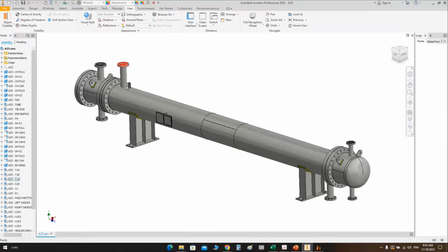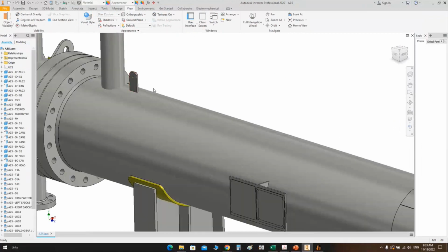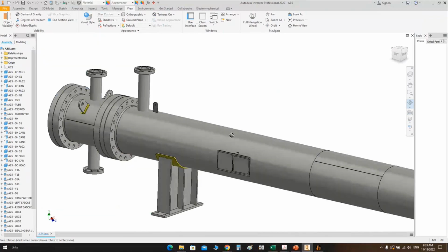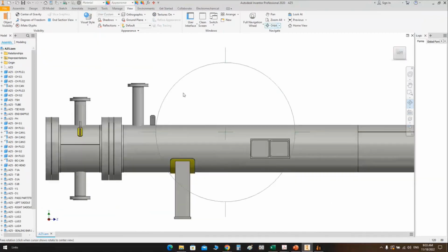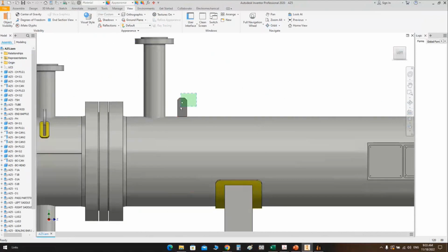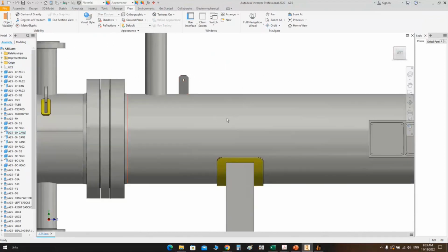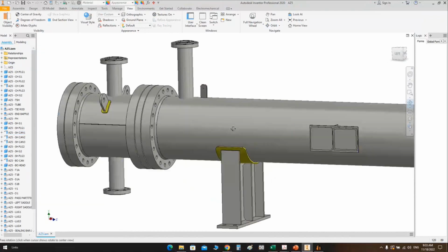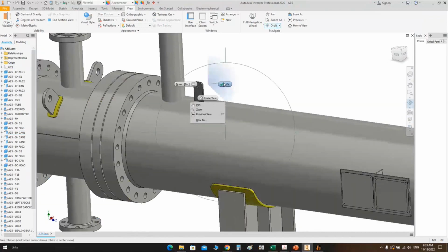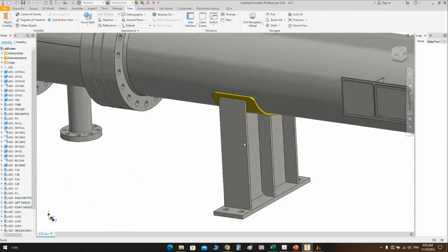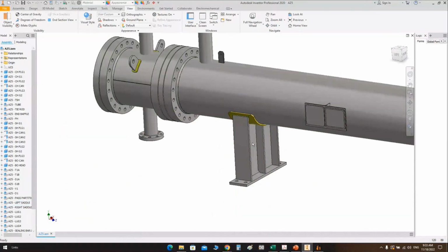Okay, now you can figure that this earthing lug is not located on the saddle, because in SEG software we are dealing with the attachments to be available only for the main elements. So you can add the attachment to the main element. So how can we move this earthing lug from the main element to the saddle on the 3D model?